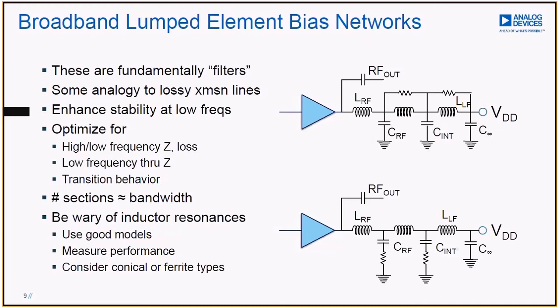And the other thing that we realize is that we're stacking inductors here. Our LRF is going to be our smallest inductor. It's the one that's going to operate at the higher frequencies. Then as we move left to right towards the power supplies, those inductors will get progressively larger as we try to create some isolation, RF isolation between the input and the output there.